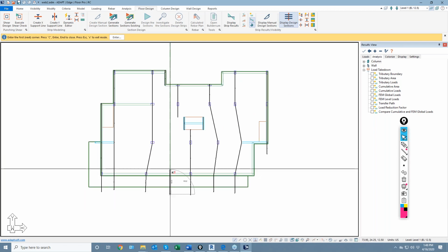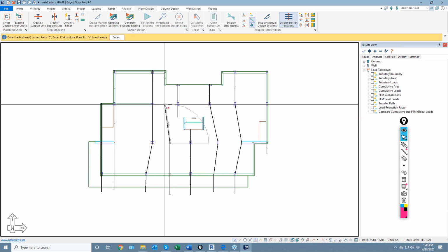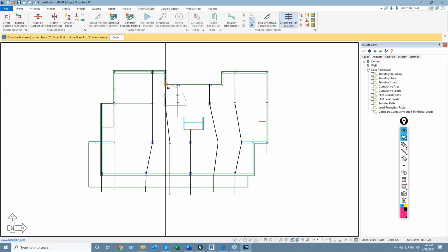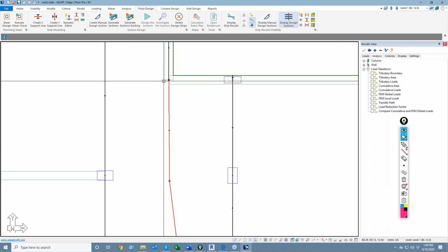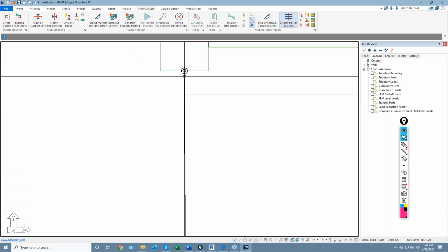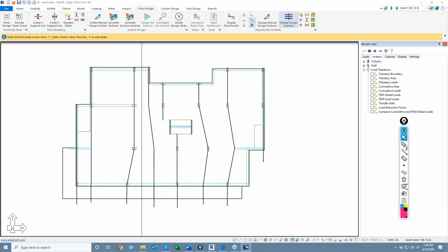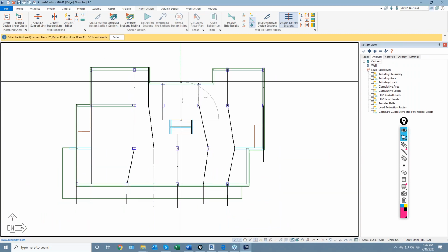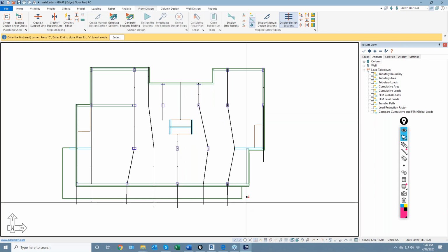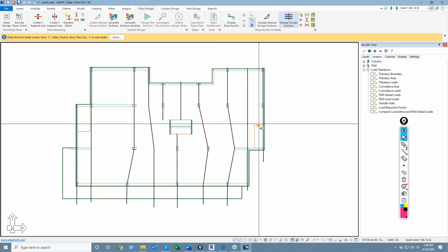And then we might have a middle strip along this path. So where does this middle strip end? Well, I might actually bend it here, and it might end up right at that beam location. So we'll make sure that those two points coincide. It looks like they're close. And then I'll do a couple of middle strips in addition to what I have. We'll go from this opening out to the slab edge, and then along this path here we have a beam. We'll just run that straight up like so.